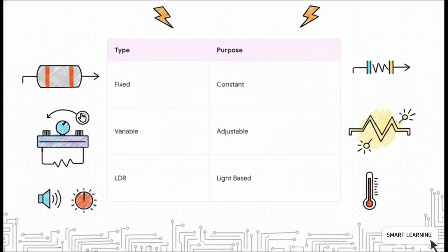Now, in real practical circuits, engineers don't just rely on random wire properties. They actually manufacture specific components called resistors to purposefully control this electrical traffic. And you've got a whole lineup of them. There are fixed resistors, which always provide the exact same unchanging amount of resistance. You have variable resistors, potentiometers, and rheostats, which let you manually adjust the resistance, kind of like twisting the volume knob on your car stereo. Then you have the smart resistors, things like thermistors, which automatically change their resistance based on temperature, and LDRs, or light-dependent resistors, which change entirely based on how much light is hitting them.